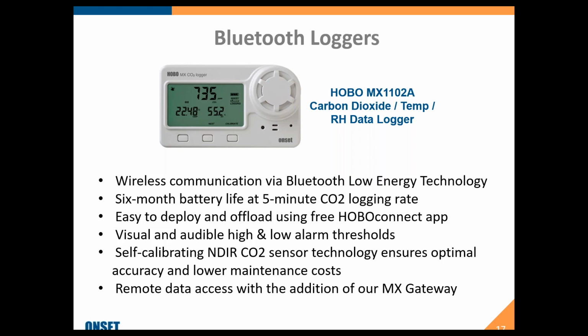Now, this particular logger here, the MX1102, does use that same wireless Bluetooth communication. So you get about 100 feet clear line of sight. It features a 6-month battery life at 5-minute logging rate. So that's something you really don't see when it comes to CO2 logging or even sensing.